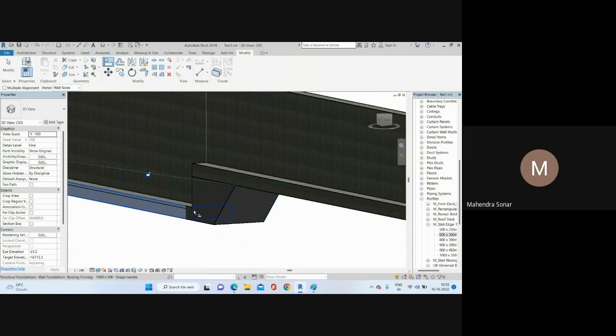Okay, so I will repeat this. You need to give the AL command. AL, I want to align this face to this face. So select this face and select this face, and you can lock. Okay, so just click here lock. So this shape is not disturbed later.